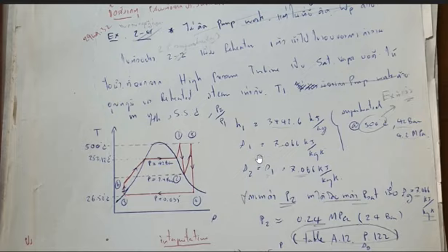Okay, for this one, at point one, 500 degrees Celsius at 42 bar, we can find the enthalpy at this point at 3,442.6 kilojoule per kilogram. We can look at the graph at 500 degrees Celsius and 42 bar, or 4.2 megapascal.